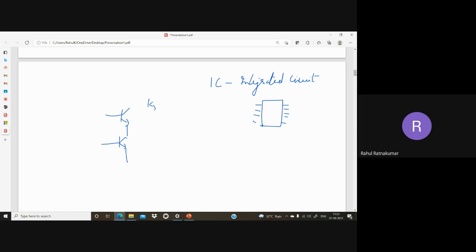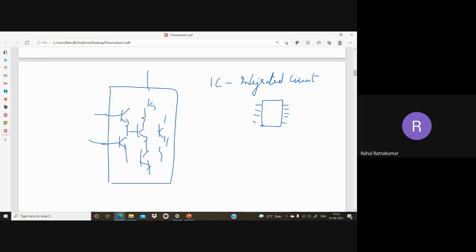So what is inside the chip? You should know that there are a lot of transistors working as resistance, capacitance and all those things. Although we try to reduce resistance and capacitance within the chip, and definitely we are not looking forward to inductors because of a lot of problems, power dissipation, delay, etc. So all these transistors are fabricated within a single silicon wafer, I will package it as a chip, and I will give the terminals. This is input, this is output. This is VDD, or we have some negative supply voltage, V1, V2, and Vout, something like this. And we have some other pins also for offset and error correction. All those things will be there.